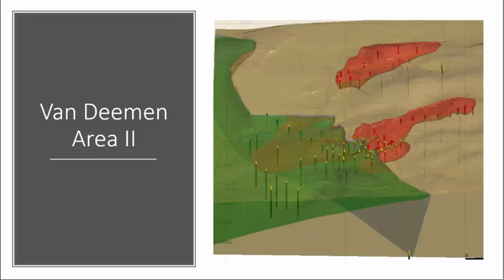Area 2 was more complex to model. We had the same lithologic units as Area 3 and 4, but we also had faulting that ran through the area. We modeled each of the fault blocks separately. Once we'd resolved the issues involved with merging the surface geology and drill holes, Leapfrog did a good job of handling the fault blocks.